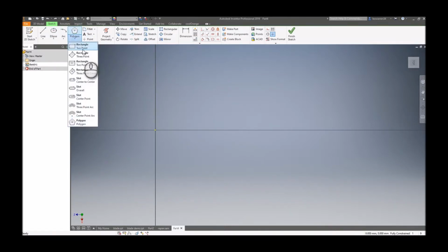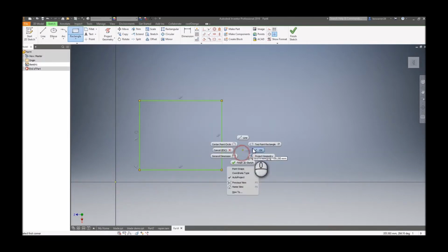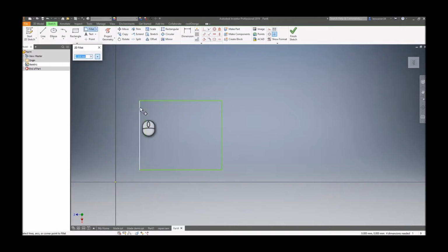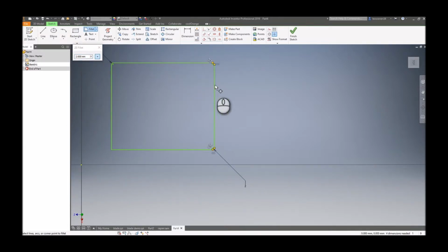Fillets are a bit more of an interesting one. So you just take your shape, and you can just apply fillets to them, and that's just your radius. And you can literally just, if you just select it and press fillet, you fillet that edge.